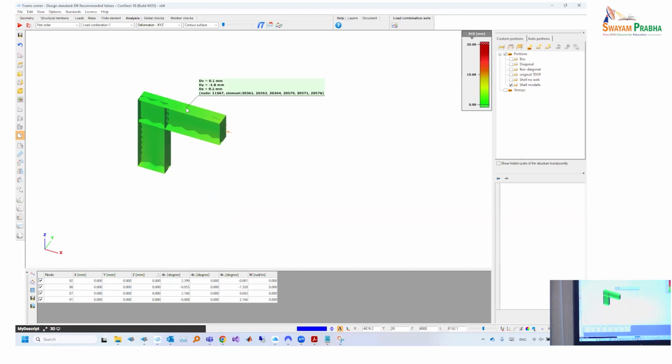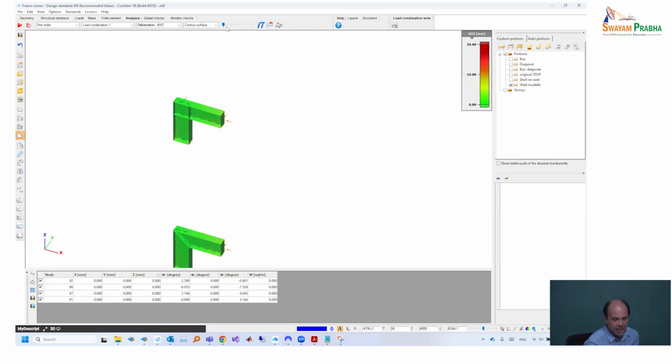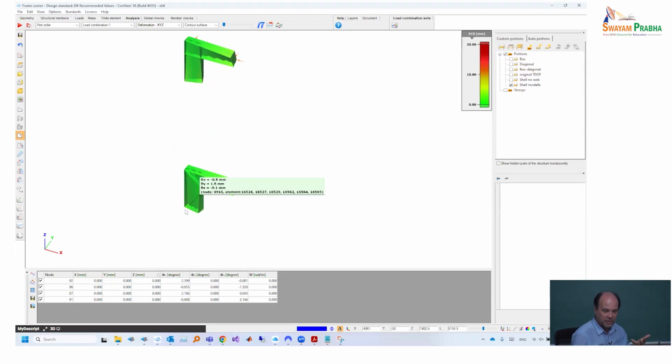For the box, which is probably the most interesting and most surprising, it gives exactly the other type of rotation than what the beam element by default would do. Our beam element by default does this. So if we just accept the analogy of the two bending moments, then we would always believe that, independent of how the connection looks like, the rotation is always like this.